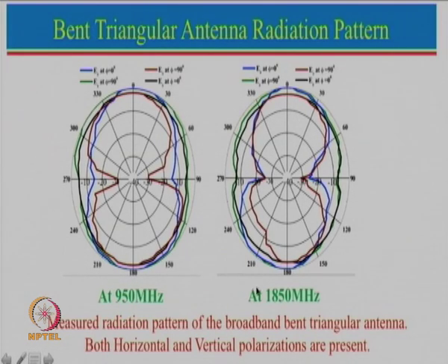So one can actually say that this particular component has both horizontal as well as vertical polarization. So this antenna can also be said to be a polarization insensitive antenna. So that means if you have this particular antenna as a receiver, you can orient it in the vertical direction or in horizontal or any other plane, it will still receive the signal. In fact, just think about it. Let us say in a mobile phone antenna, if we just use a normal monopole antenna, that will have only vertical component. So that means it has to be perfectly aligned with the transmitter, and which should come over here.